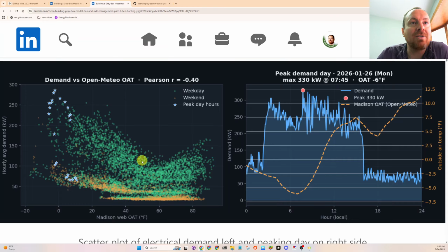When the weather is mild, in this band from 40 to 60 degrees Fahrenheit, you can see it in the data. If your optimal start algorithm is working properly, it would be just bare minimum run hours for that HVAC: when school starts, when school stops, and nothing on the weekends unless there's some kind of event or after hours. And then as the weather gets colder, the optimal start algorithm just increases startup times as needed. So they must have a really good optimal start algorithm.